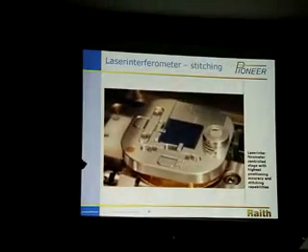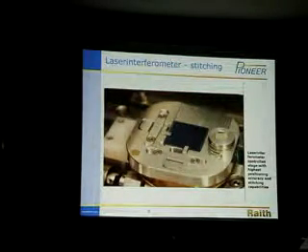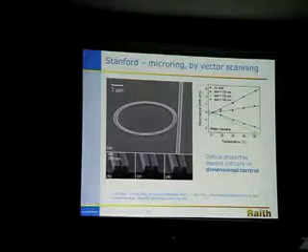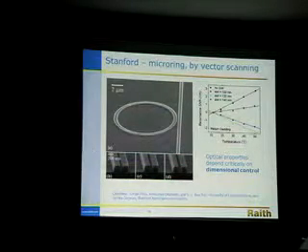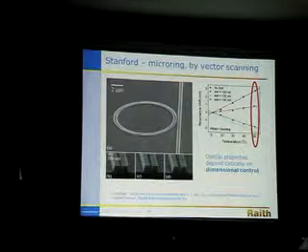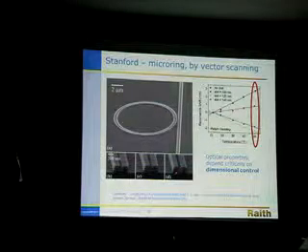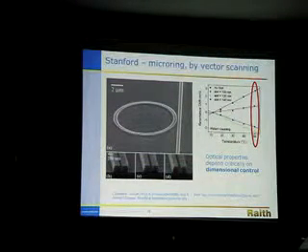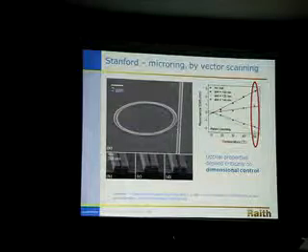So this is the Pioneer's laser interferometer stage. It's moving at the scale of a 2 nanometer precision. And so with the laser stage, you're able to stitch together large patterns. So waveguides are often very long and need to be stitched together using the laser interferometer stage. And this is a 200 nanometer scale bar. You see the slots are varying ever so slightly, just by a few tens of nanometers. But the performance of each slotted device shows a very, very drastic difference.